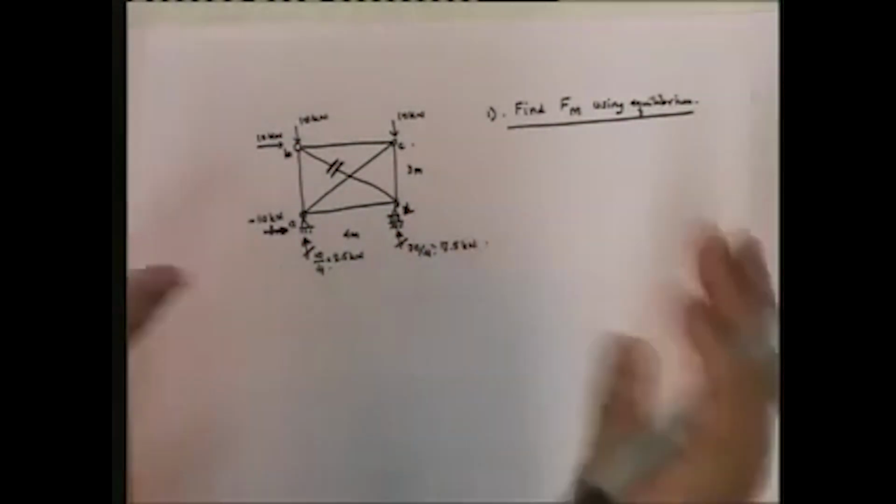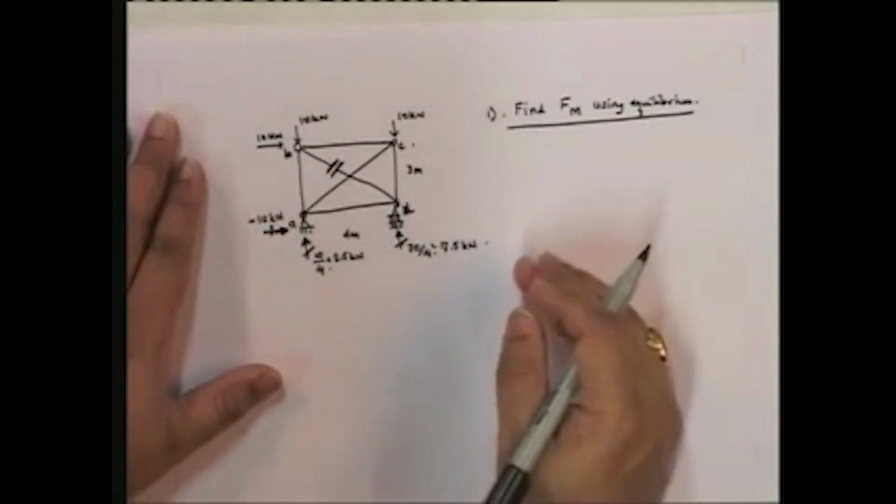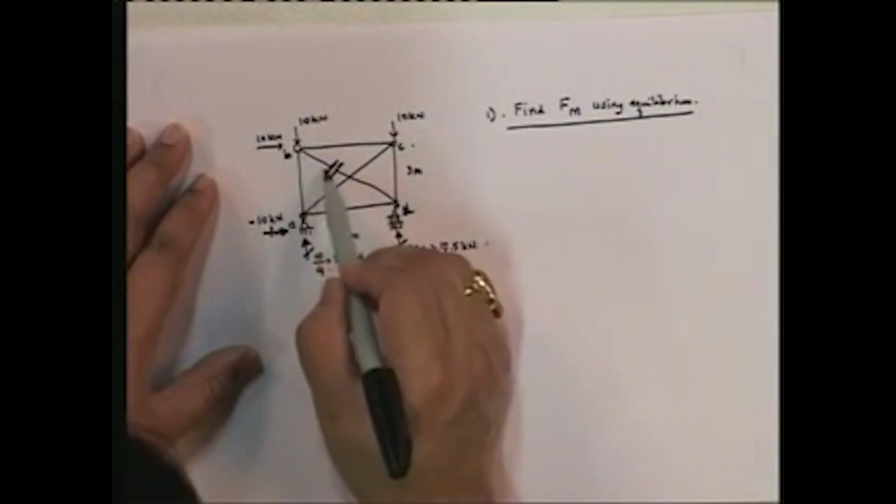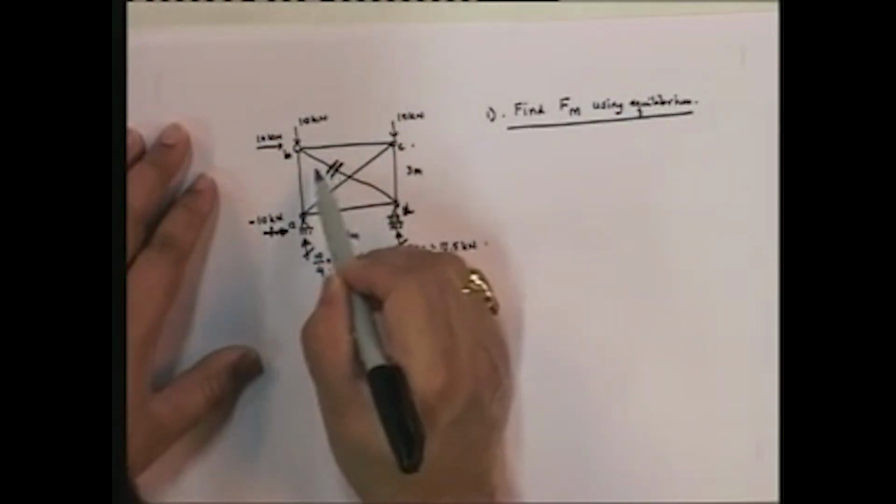Okay, so we've got the reactions for the support. Once we have the reactions, of course I didn't really need to do that, but it's a good idea. Now I can use the method of joints to find all the forces in all the members. So let me start off with a simple one, B. Member B, note that although it exists, I know that the force is 0 in this.